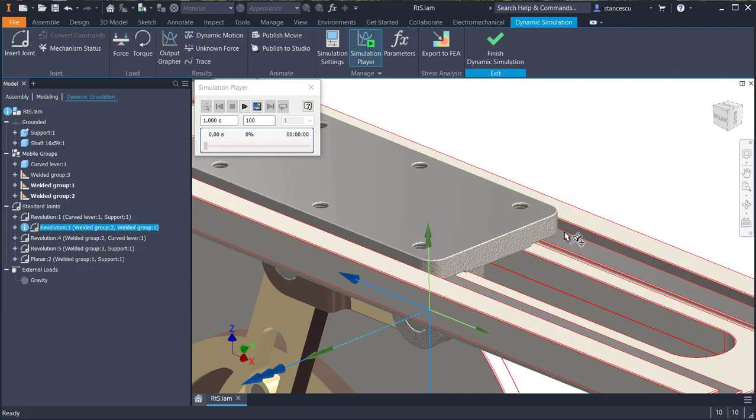Yes, we don't need this because that degree is constrained here. We cannot admit to have the same degree at the same part to be double constrained, in fact. And what can we do? We have to use here not 3 but 2 degrees of freedom with a mate.